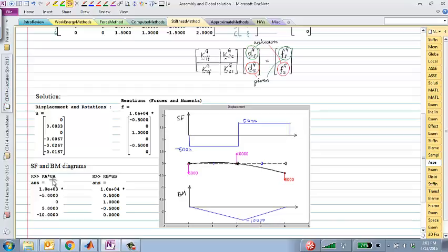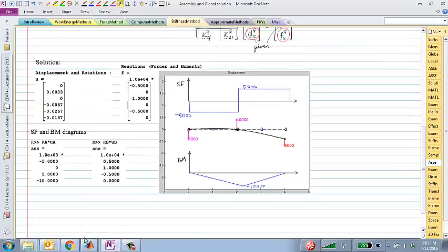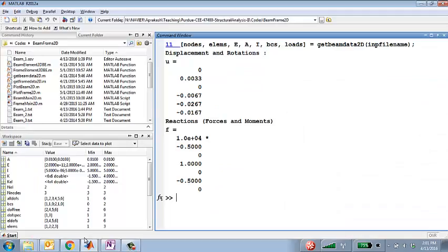The good thing about beam problems is that everything is horizontal. So you don't need to do any transformation at all. You just go to element 1, for example, and find out what the element degrees of freedom are. So I'll do that maybe on the screen. I have my global displacement vector, which is a 6 cross 1.